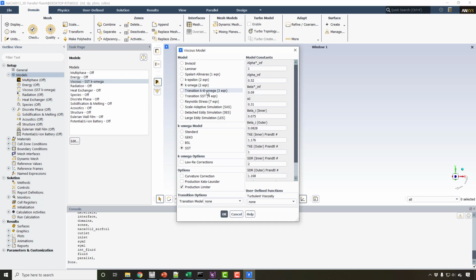So if you don't simulate that portion of the airfoil, especially at 0 angle of attack, you will get an error in drag coefficient as much as 100%. If you take a look at my simple airfoil mesh, the 2D airfoil mesh which I created like 6 years ago, you will see that in that case we have a very large error, and that is coming from when we don't model the proper turbulent and laminar regions, and we get that issue.